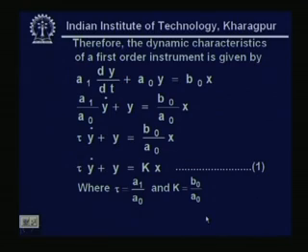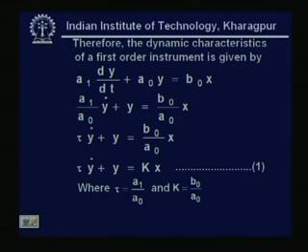Obviously, all this, the time constant of the system, like as you told, because if you take an example of a thermometer, this A1 upon A0 and static sensitivity B0 upon A0 depend on some of the physical parameters of the system. What are those physical parameters? That means what is the size of the bulb of the thermometer, the materials which you are using as thermometer liquid, all these factors will actually tell you the value of the tau.